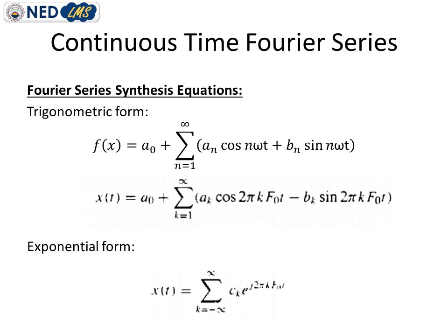So students, we have derived the trigonometric expression for the Fourier series, and this equation is the synthesis equation of the Fourier series. As you saw from the example, we are combining multiple waveforms to formulate a complicated waveform. So this is the synthesizing of components to formulate a complicated or final output.